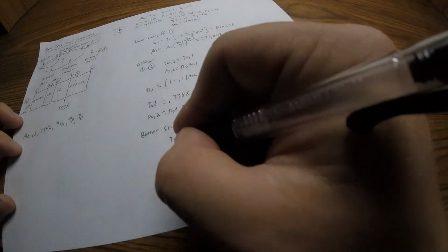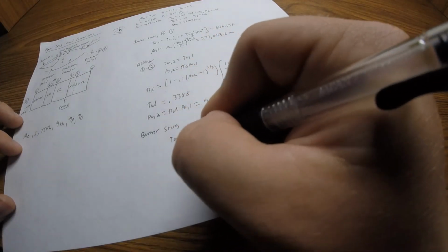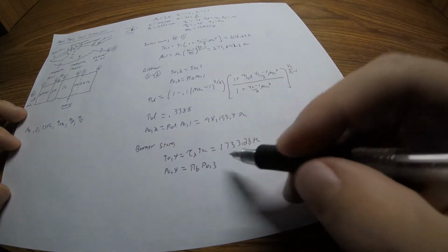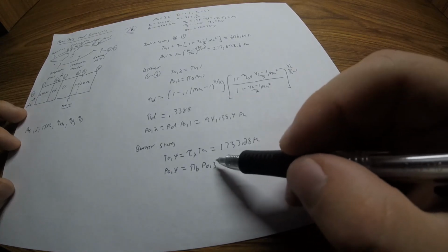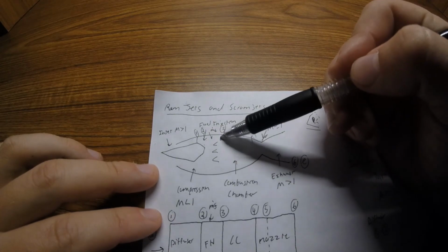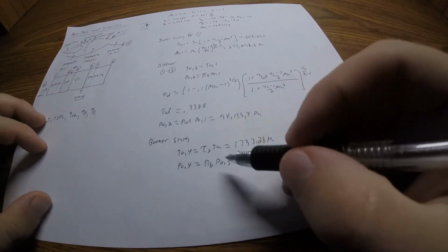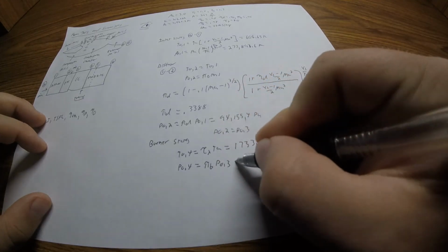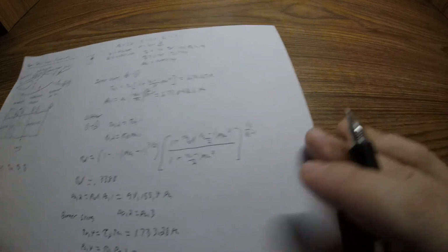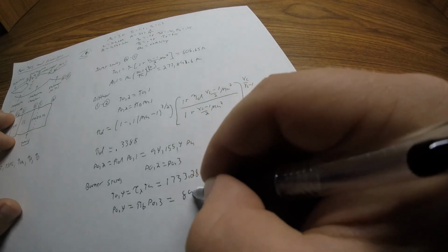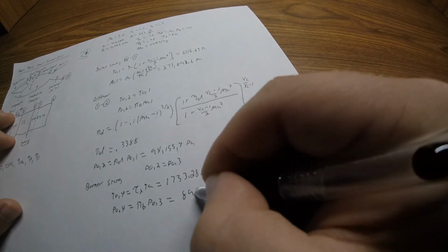And then we can find our pressure at state 4, which would be pi b times PO3. And we are going to say that PO3 equals PO2. So we're saying that there's not a significant pressure difference between states 2 and 3, which makes sense. So we can call PO2 and PO3 equal to each other. Write that down. And then pi b, we are given that, and that is 0.95 for this equation. And that would equal 89447.63 pascals.